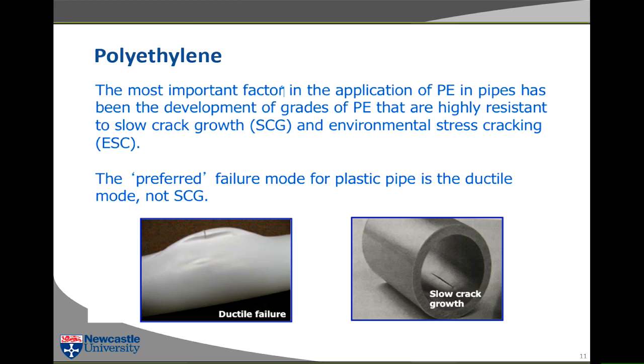And this always starts at some concentration, some stress concentration. The example that I've shown you here is a scratch on the bore of the pipe, which has acted as a stress concentration and caused this thing to grow. But I've described also, we talked about welds. We talked about hot welds in pipes.